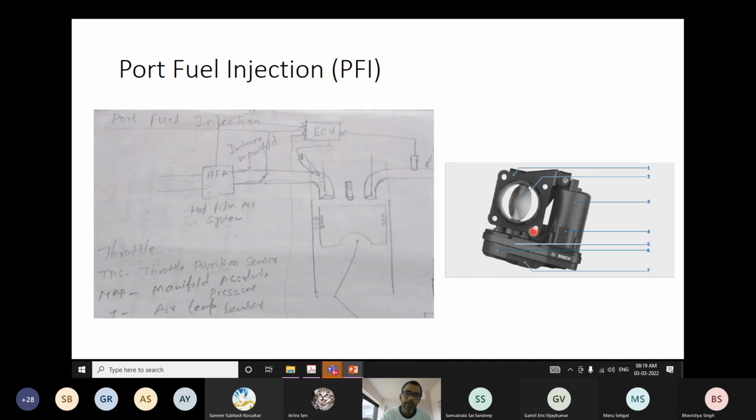So it depends upon what kind of calibration or control strategy you have developed in your ECU. Accordingly, the signals are going to flow. Initially, it was based on the acceleration position. Now it is based on torque based demand. Further, people are thinking about IMEP based calibrations also. That is the story. It all depends on what kind of control systems you are developing. Accordingly, signals are going to flow here and there.